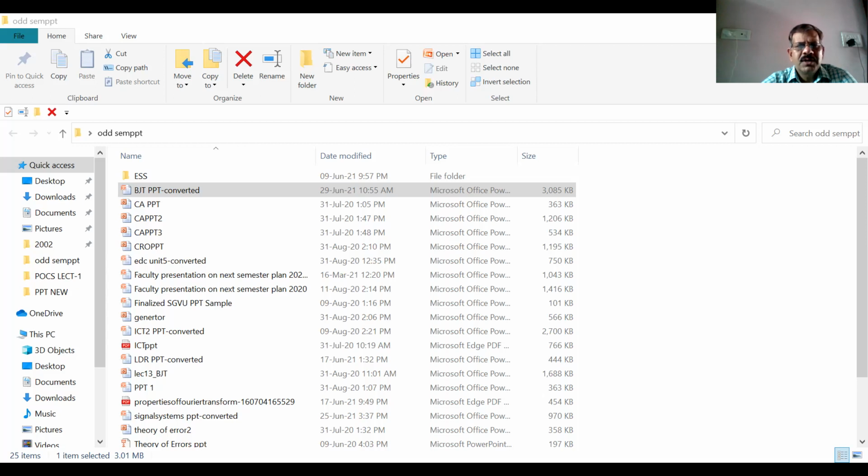The junction between emitter and base is called the emitter-base junction, or emitter diode. The junction between base and collector is called the collector-base junction, or collector diode. The emitter diode is always forward biased and the collector diode is always reverse biased. The resistance of the emitter diode is very small and the resistance of the collector diode is very high in the reverse biasing case.